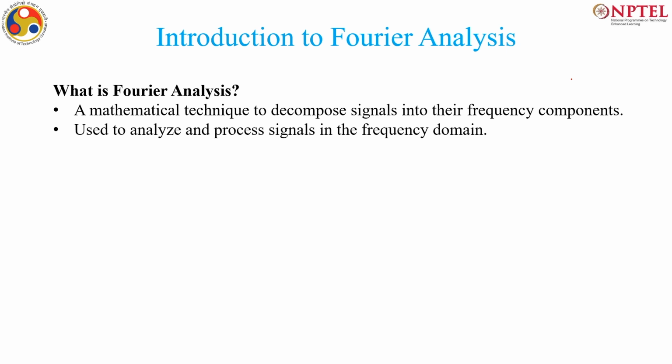When I am speaking, my audio signal will have a specific frequency content, whereas there is some background noise which may be of a different frequency range. By observing their Fourier analysis, we can determine which portion is my signal and which portion is noise, and we can easily filter them out.